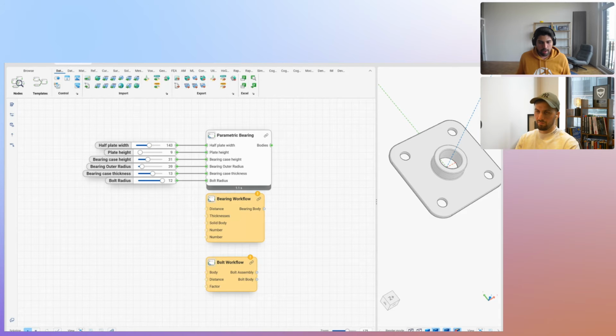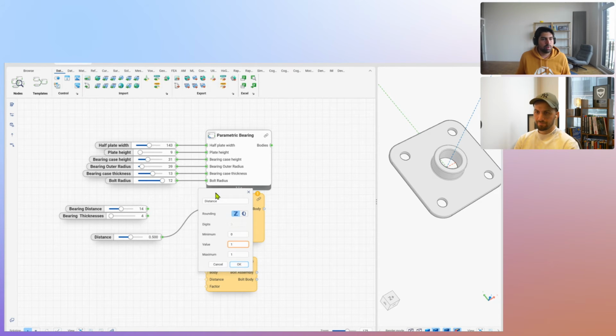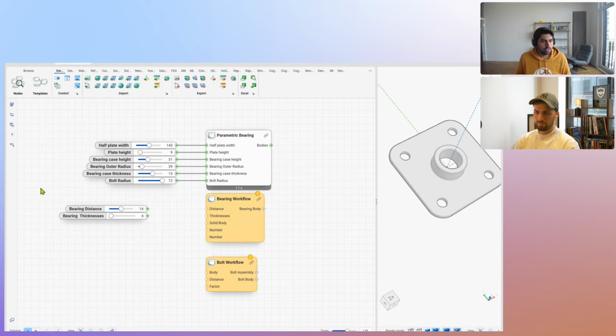In a similar way, I can also do it for the other. The way I would usually do it is to drag it here, put up a number slider, and then define a minimum to maximum value. So we really parameterize these values. Let's say I give it 20 or things like that, and then I can always vary the distance here. Let me just plug this in.